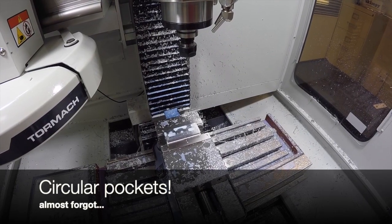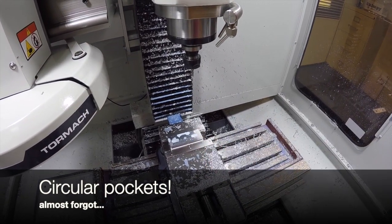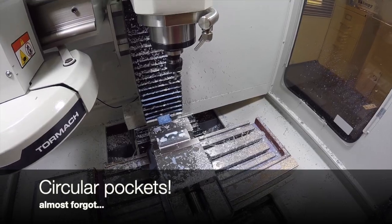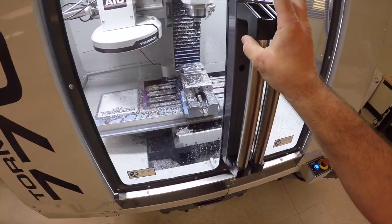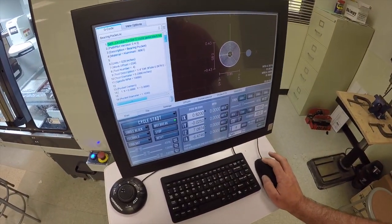Okay, here we are about to start the large pocket that goes right in the middle. It's about 1.103 inches in diameter, still using that 1/4 inch end mill. I'm going to hit cycle start now.